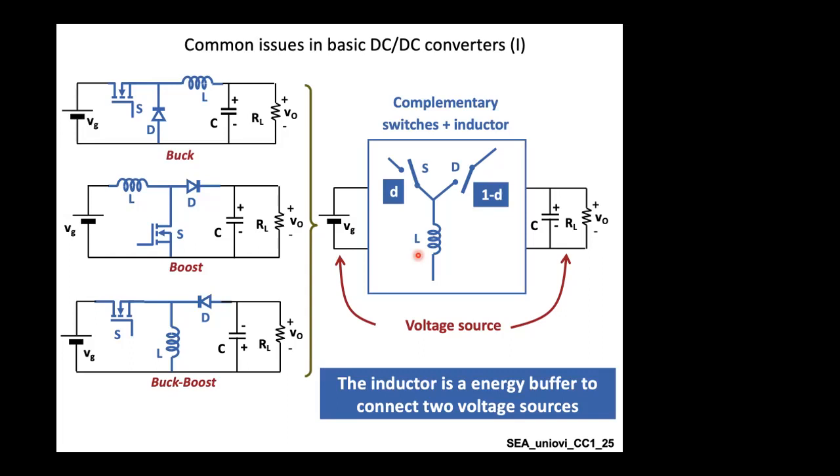However, if you pick up literature, if you Google and search for papers on that, you will find an endless number of other topologies to perform the same function. And herein, there will be a very challenging trade-off between various parameters to evaluate a DC-DC converter. Maybe by the end of the lecture, we will consider this, or maybe in another course. And also there is another family of DC-DC converters called inductor-less DC-DC converters, whenever you are going to scale up or scale down your DC-DC converter to the CMOS level.